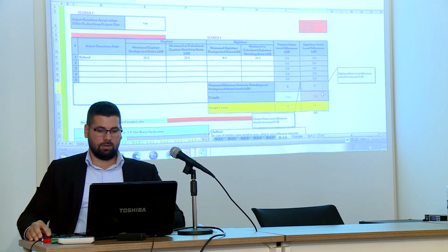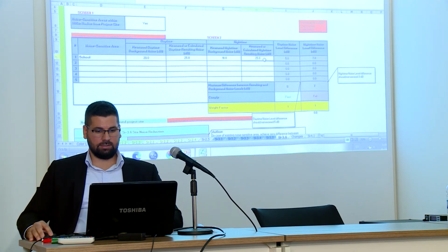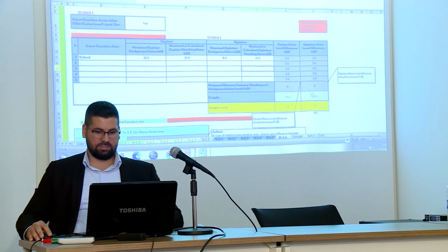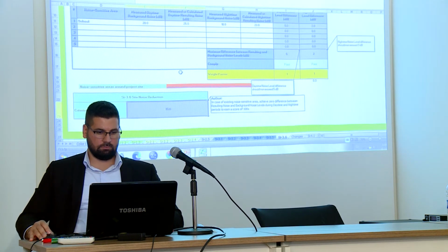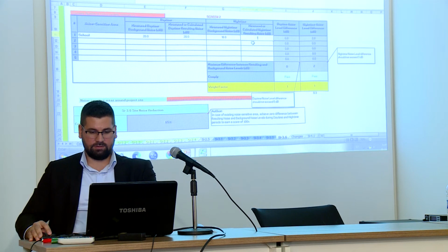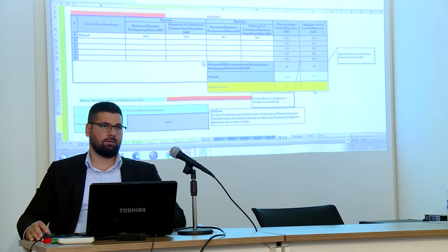Okay. We have different criteria for indoor noise. In order to meet the nighttime noise criteria, we have to lower this to 20, so the difference is 2, which is lower than 3. It passes. And in order to earn a score of 100%, these differences should be 0. So we should have 20 here and 18 here, and then we can earn a score of 100%. Each 1 dB of additional noise will affect the score.